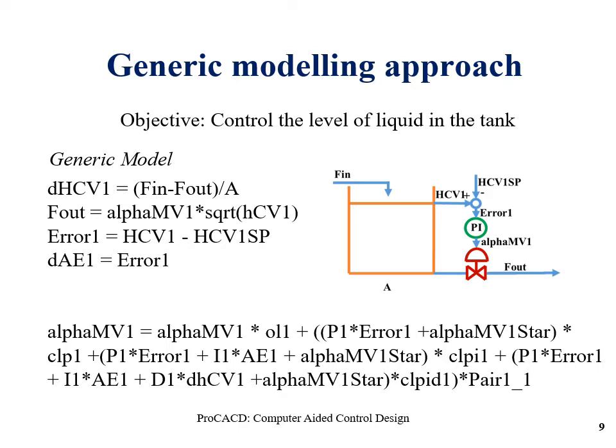Here OL represents the open loop binary variable. If you keep this binary variable as 1, then it is just open loop, and there is no control action, because the right hand side of the equation is the same as the left hand side. Of course, once you set a binary variable to 1, all other binary variables are automatically turned to zero.